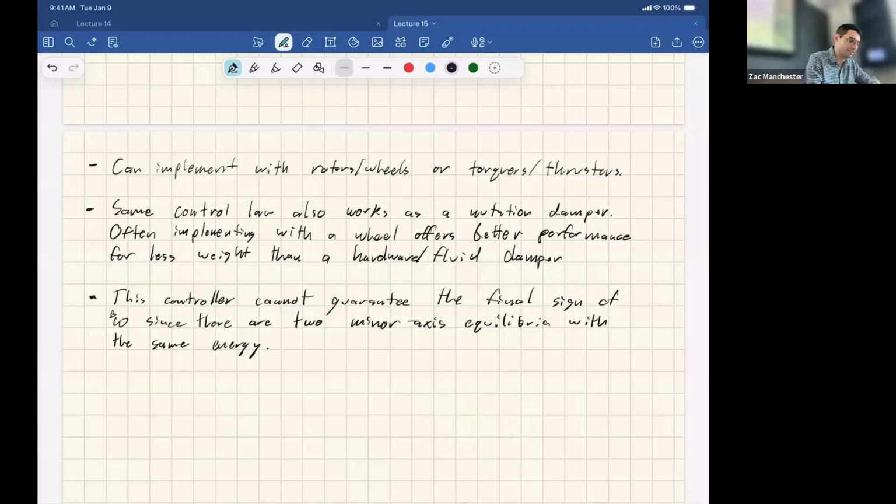So the gist is you want to array the last one in such a way that, obviously you don't want to double up. What you want is for that fourth one to have some component along all of the other axes so that you're single fault tolerant. Basically, if I lose one of these, I still span R3 with the remaining ones, no matter which one fails. So the most basic thing is you want to make sure that no pair are linearly dependent, such that I'm always single fault tolerant.